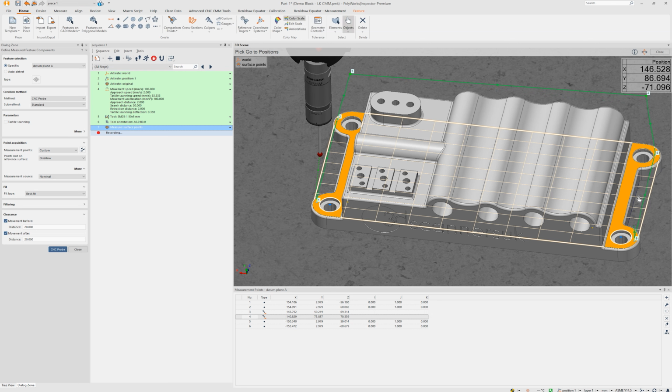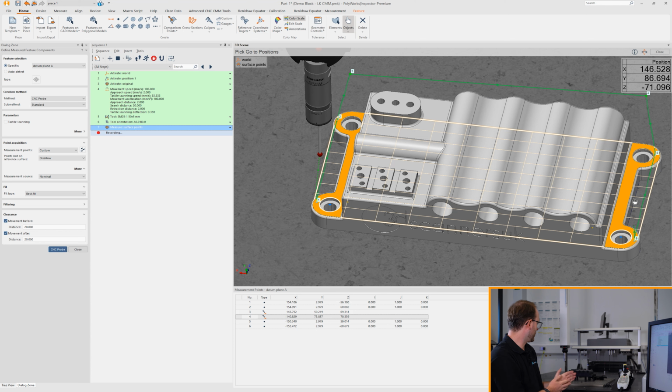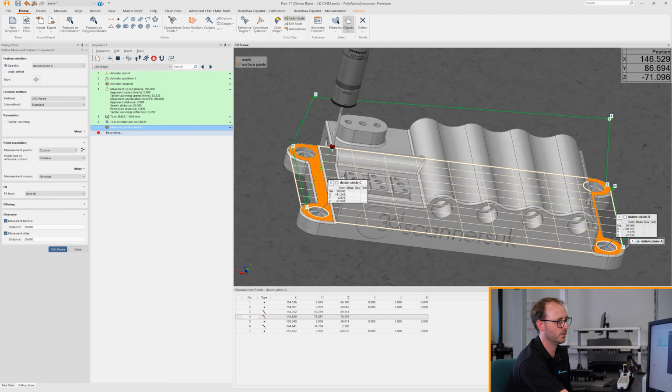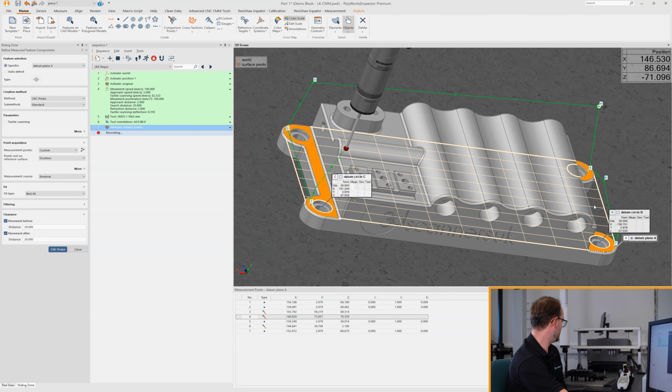Again, all green. One thing to be careful of, on the bed behind me, we have a tower clamp, fixture kit, essentially between the 2 holes. So what I need to make sure is that the path between 5 and 6 is just going to clear it. So what I'll do, click on this one as well, and I'll just stick that a little bit higher over the top of that. Okay, so if I then right click to confirm, I can then have a look. Everything looks green. Seems to be no collisions on the fixture.